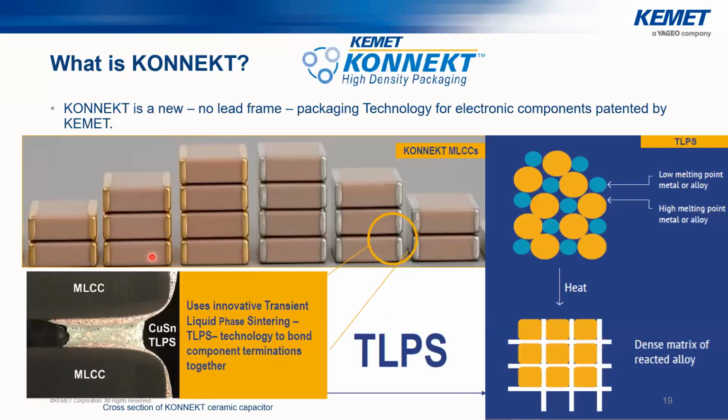And for this reason, we have developed internally what we call the KONNEKT, which is a no-lead frame connection between several capacitors in parallel, which is based on the TLPS, a technology used to bond component terminations together, transient liquid phase sintering.